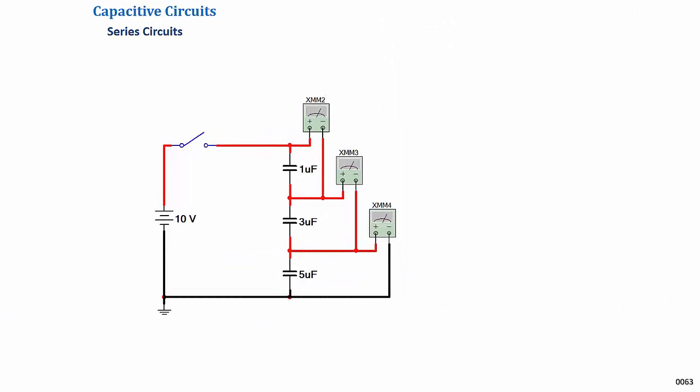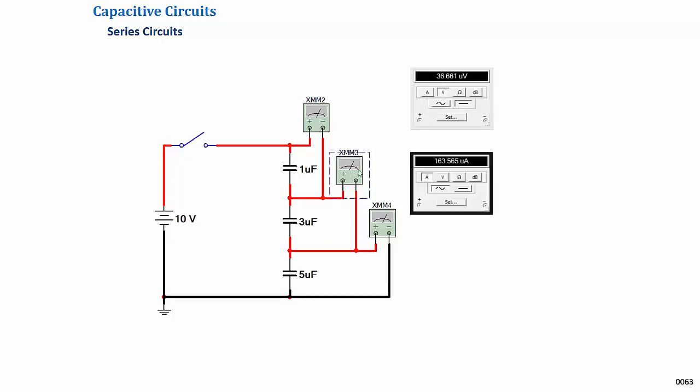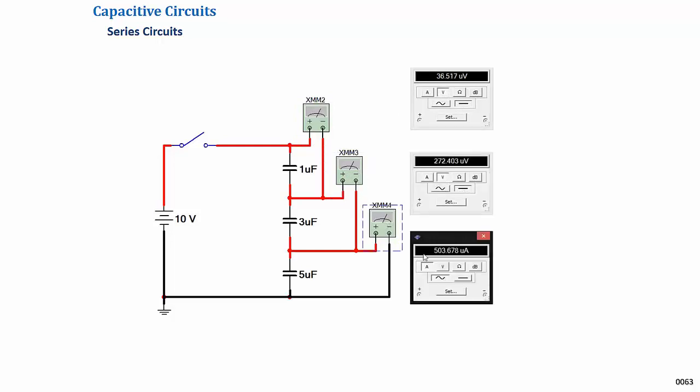This video clip is a simulation of the example and shows how each capacitor voltage would be measured in practice. A DMM is connected across each capacitor set to read DC volts. When the switch is closed, the DMM values are the same as those calculated within experimental limits.